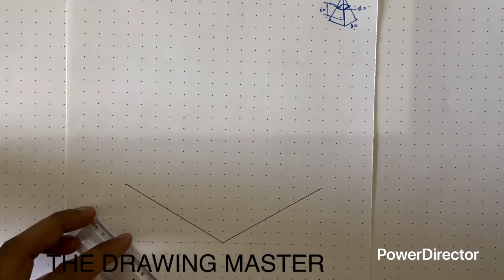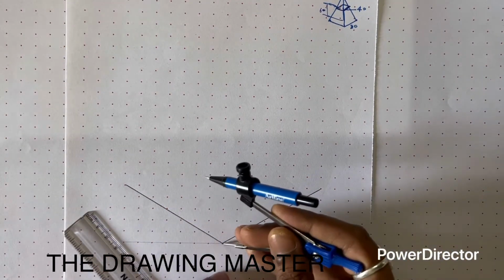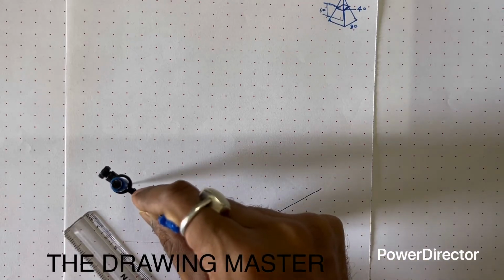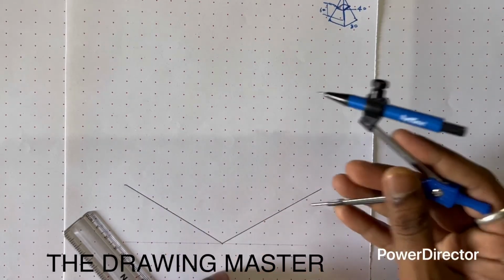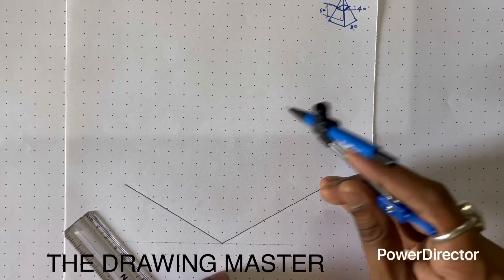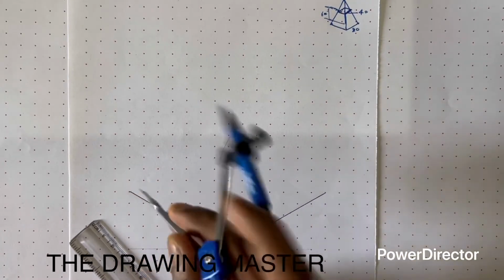So now we'll generate the rear edges of this square base. Let's copy this dimension 80. We have to take 80 from this side and similarly 80 from this side.